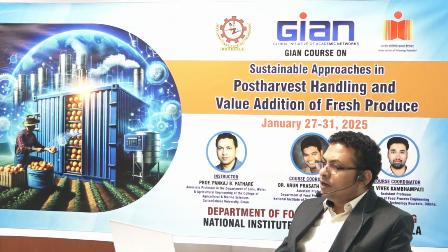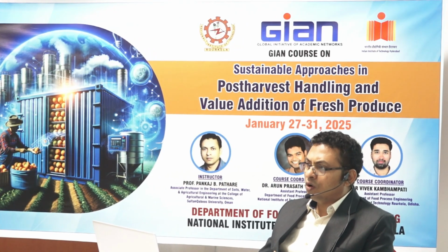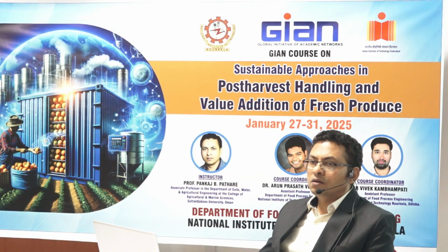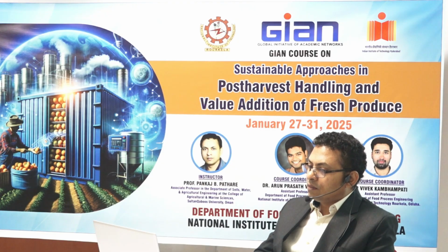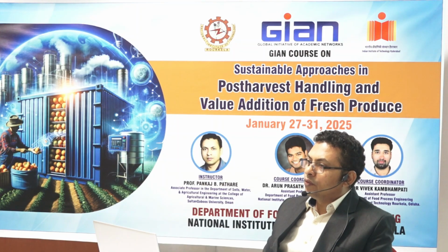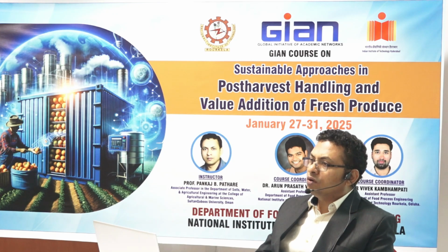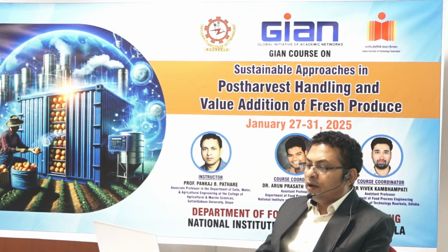We create ozone in two ways: corona discharge or UV rays, and those are commonly used, creating the ozone with an ozone generator. When we generate ozone in the process, it's not only O3 that we get. With the O3 we may additionally get other substances, including hydrogen peroxide, nitrogen oxide, or nitric acid, coming with it.